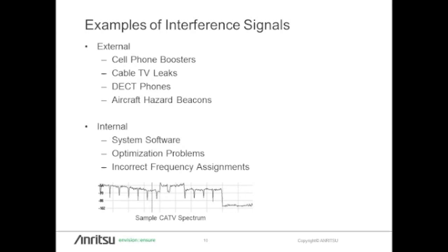And then there's a whole different way you can approach the interference hunt once you say that there are cable TV leakers. Because a lot of these cable TV problems are prevalent in neighborhoods. They're deployed in the neighborhood at the same time, so they tend to go bad almost at the same time. So you can see multiple leakage points, where different connectors wear out, and you find that radiation does leak out.